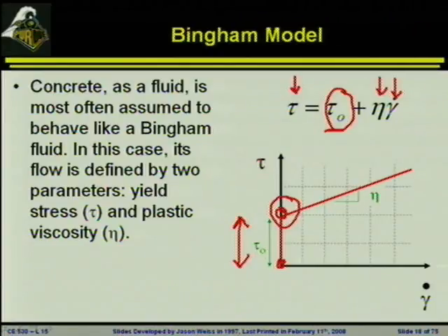Right, most of you got up this morning and you weren't clever enough to instantly take the cap off of the toothpaste and have the toothpaste jump out and onto your toothbrush, right, because it wasn't a Newtonian fluid. You took advantage of the fact that it was a Bingham fluid because you took a few seconds and applied a yield stress by squeezing the tube to get the material moving. Same type of thing that we have when it comes to concrete. Now, the one thing that I will mention is the water reducers that we're talking about, what they are typically going to be acting on is this yield stress value. The big goal of a water reducer is really to drive down this yield stress value and make a material try to look more and more like a Newtonian fluid.